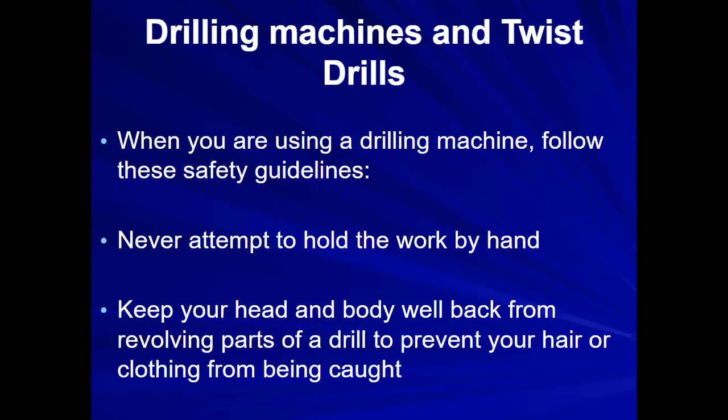That applies to drill presses, that applies to hand drills, that applies to angle grinders, as well as pedestal grinders. So we never want to hold anything by hand, because you are not going to win that battle. It's just not worth it. You want to keep your head and body well back from the revolving parts of the drill to prevent your hair or clothing from being caught.